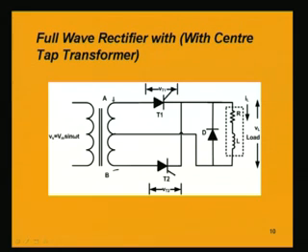So, in this situation the upper thyristor, that is T1, will be forward biased, or anode will be positive, and it will be conducting at an angle of alpha, say. Both are identical thyristors, we are assuming the delay angle is alpha.